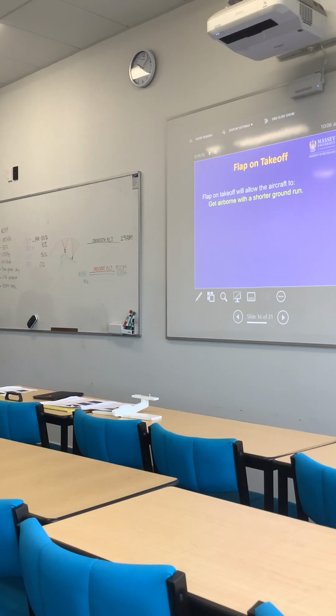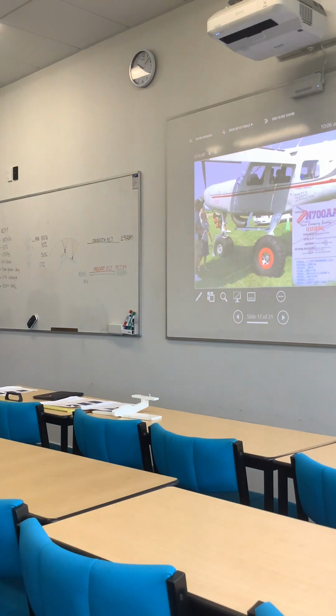But then as we learned in the climbing and descending briefing, flap reduces the rate of climb and the angle of climb. So we only really gain a benefit of it to get off the ground. So we tend to raise the flap pretty early once the aeroplane is airborne at a couple of 100 feet and a safe speed. Otherwise, it doesn't serve any purpose anymore. So run through that with them.